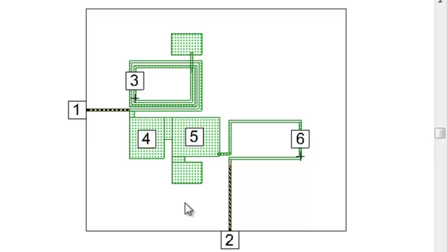As a designer, you have intuition about how much change would affect a certain amount of shift in the values of these components, or you could create a parameterized Sonnet project of each one of those structures and sweep those values in order to create a family of curves so that you could see how much inductance is increased when you shift the lines. Let's say stretch the inductor by 10 microns or 20 microns.